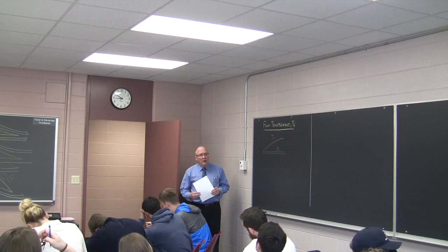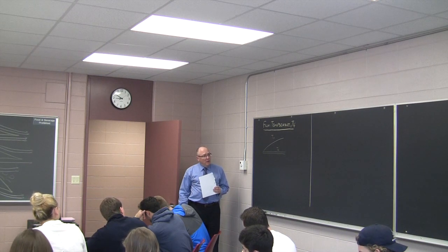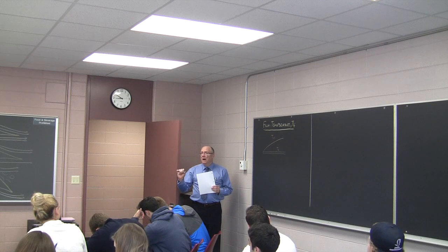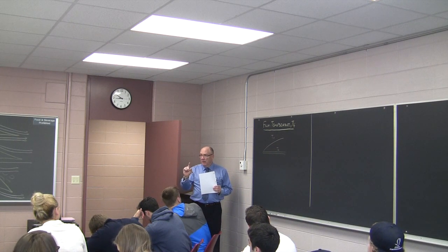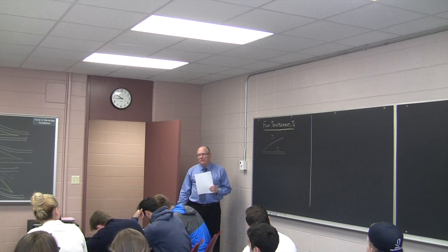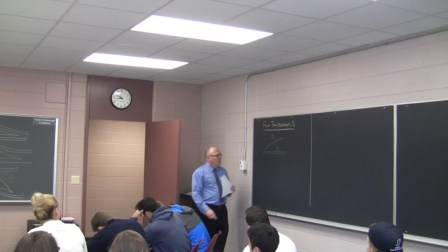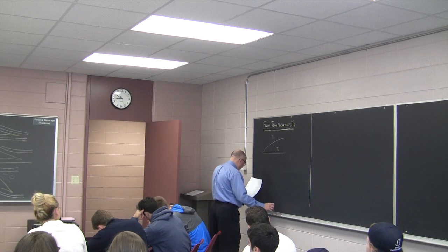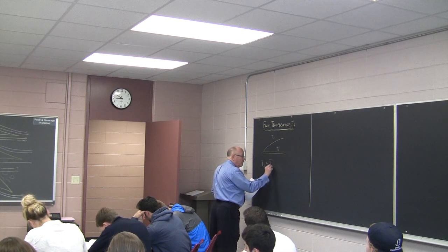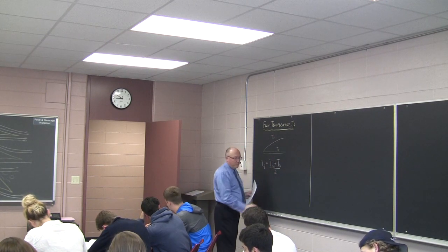One of the reasons why your correlations didn't work out quite as well for the transient ball experiment is that the surfaces aren't isothermal, they're constantly changing. But the film temperature is defined, TF, as being equal to T infinity plus TS divided by 2.